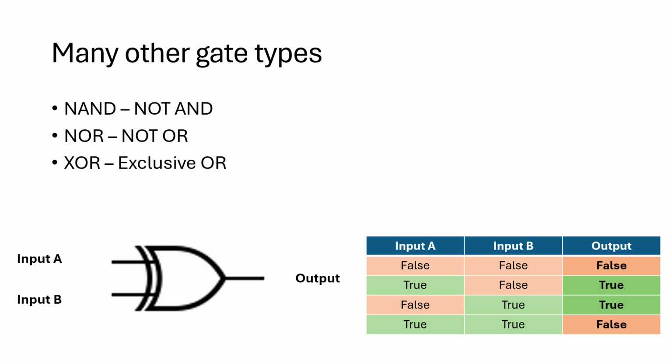The XOR gate is slightly different. It's what we call an exclusive OR. So it uses the X as exclusive. Okay. It works very similar to a normal OR gate, with the exception of that final one. They have to be exclusively true on A or B. Okay. If they are both true, then the output will actually be false. That pretty much covers the basics of different logic gates. There are many other different types out there. Like I say, for the most part, they're combinations of those 3 core gates.